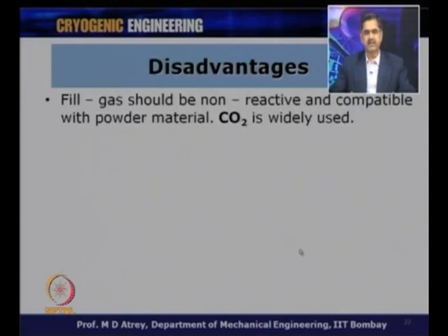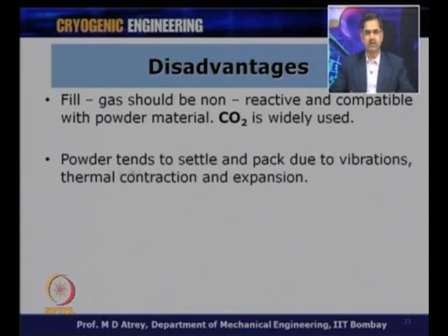The disadvantages in this case: the fill gas should be non-reactive and compatible with the powder material. CO2 is again widely used, and this is true for the earlier insulation also, that it should be non-reactive and compatible with the powder material. Another disadvantage is that the powder tends to settle and pack due to vibrations, thermal contraction and expansion.